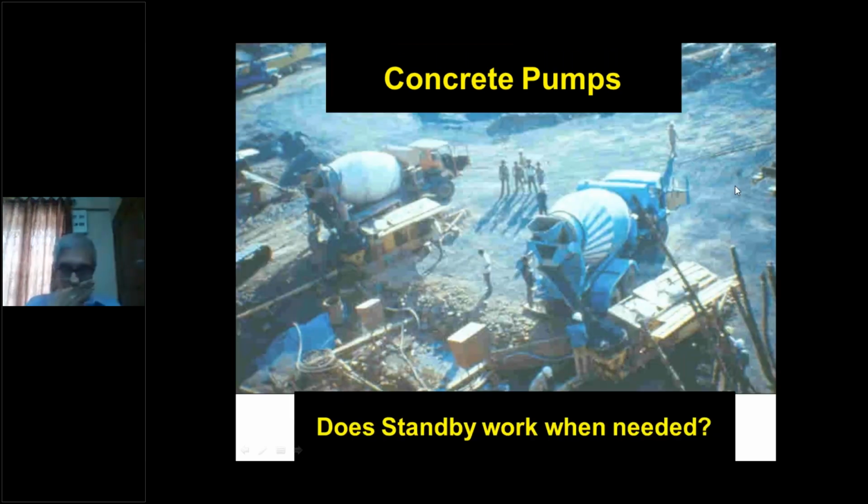Concreting has to be done in a correct manner. The transit mixers should be able to approach the pump from both sides, so that in case one side gets redundant due to waterlogging or whatever problems, or the transit mixer himself has broken down and cannot be moved away, the pump can be approached from the other side. A standby arrangement is almost mandatory when you do large concrete pours. This is very, very important.